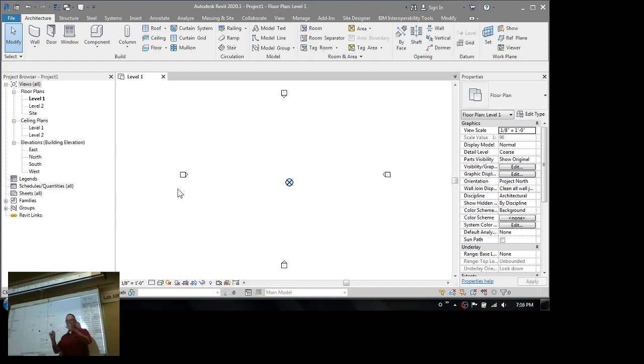When you draw a line in AutoCAD, you type L, space, and then 0, 0, that's 0, 0 in AutoCAD. You need to make sure that there's no data that's outside of that 10-mile limit and then gets imported into Revit. And you're like, well, why? What's the big deal?